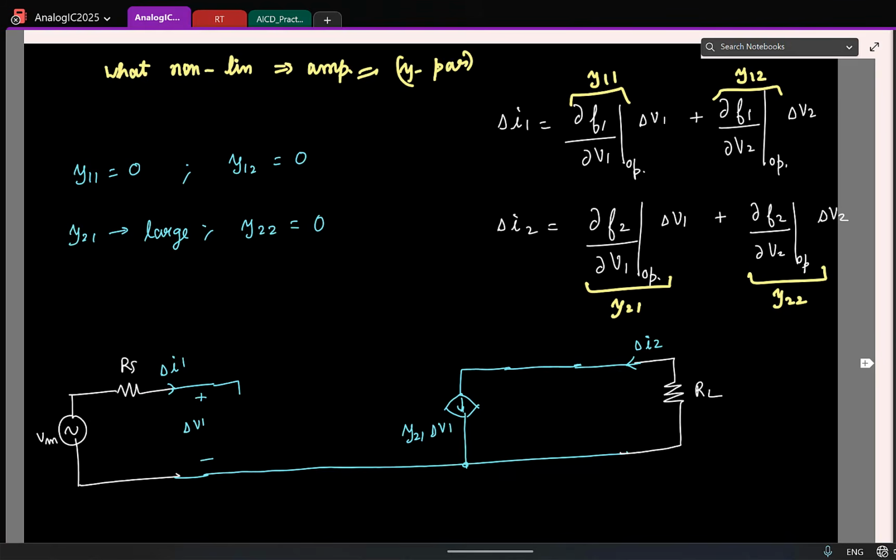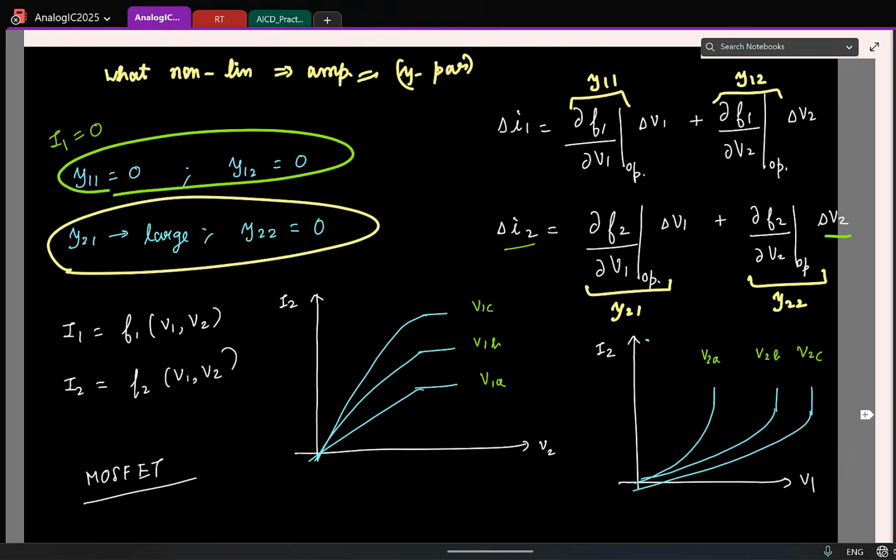So now, from the understanding we had on the small signal Y parameters, we try to sketch the nonlinear characteristics. We know that Y22 is 0 for small signals. Y22 essentially relates the second port current with the second port voltage. So if I sketch I2 versus V2, around small signals in a range of voltages, the slope is going to be 0. That's what we got, a 0 slope, and the actual characteristic looks like this.